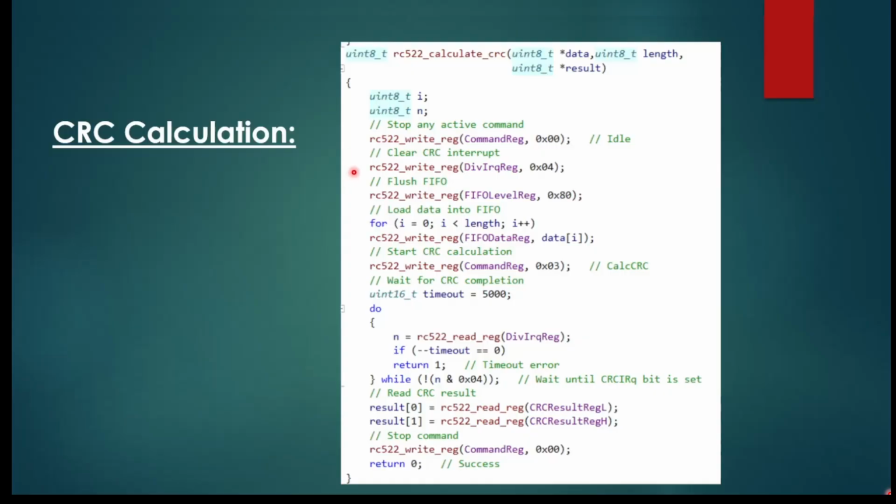Next, we're going to know that the CRC is complete and we can go get the data by looking at the reader registers. So the next thing we do is clear all the interrupts, I should say the interrupt register. So what we do is we clear all the CRC interrupts.